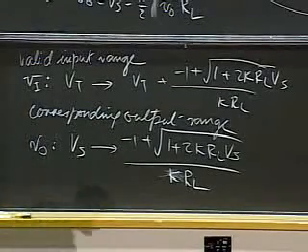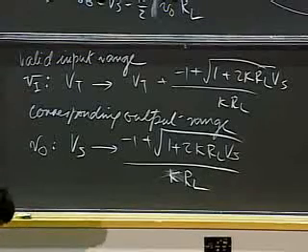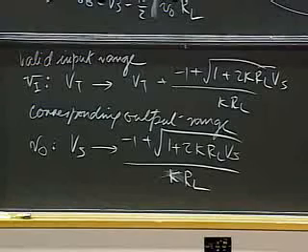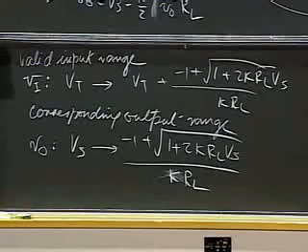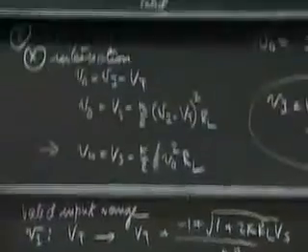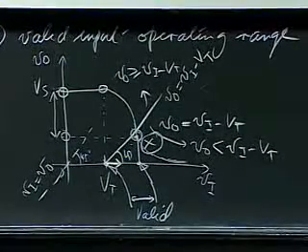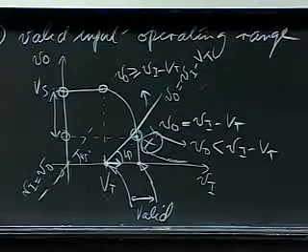Let me go back and quickly show you a little MOSFET amplifier circuit, so you can stare at a real transfer curve yourselves and convince yourselves that, roughly at the point proportionally shown in the curve up there, the MOSFET indeed goes into its triode region and begins heading out of its saturation region. Can we show it up there?